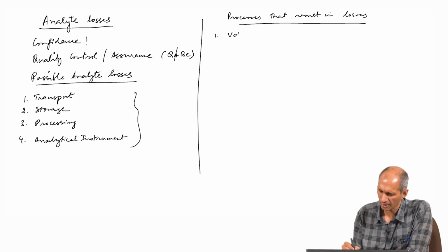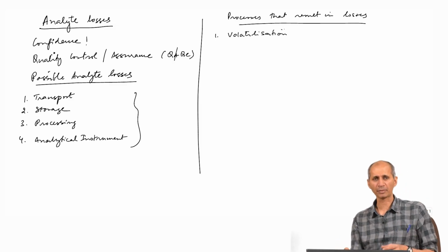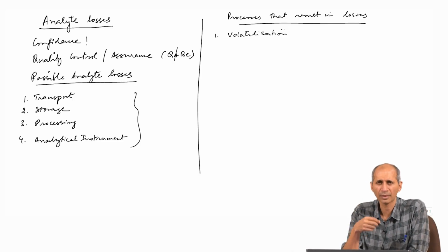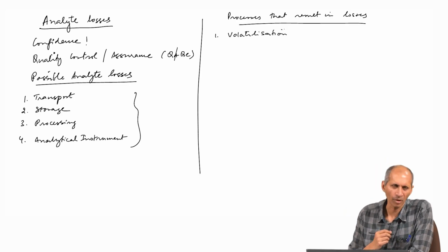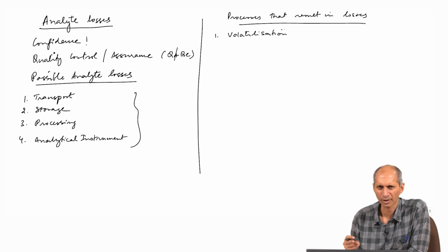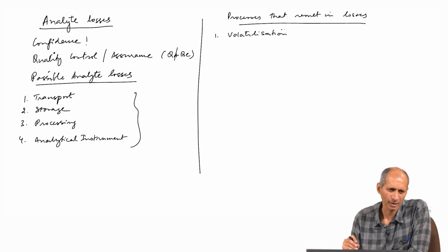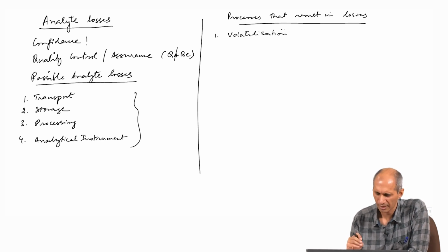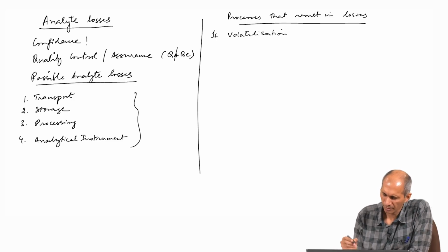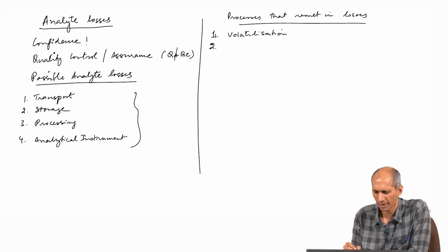One of the main first things is volatilization, which is the evaporation of the analyte from the water sample or the filter or anything. Whatever we are going to discuss here applies to analysis of all matrices, whether it be water, or an air sample using a sorbent or a filter, or extraction of an analyte from a sludge or soil. It is common for all of them, so you just have to adapt it. Volatilization essentially is evaporation. We will come back to how to assess it.